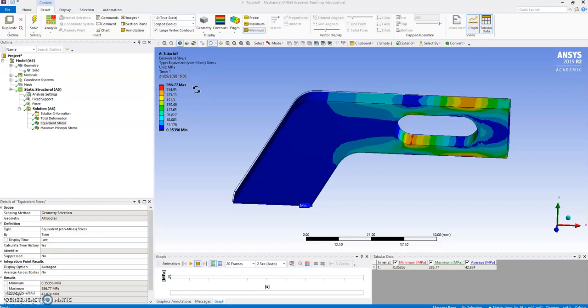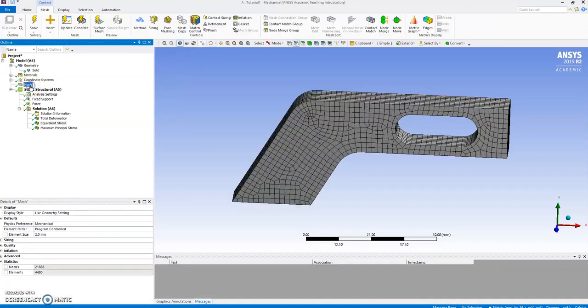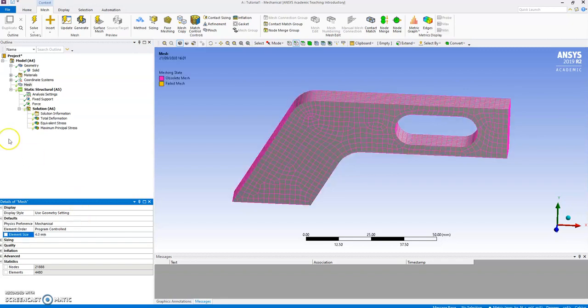It's quite important to appreciate that the values given by software, even if they have large accuracy, like 2 points behind the decimal in megapascal, are nowhere near that believable. So, to convince you, first of all I'm going to change the mesh. Let's change the element size to 4 millimeter. Make it twice as big, so that should have around 8 times fewer elements. Let's update that mesh.